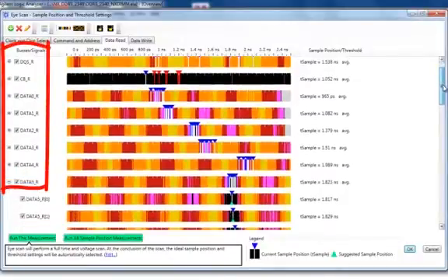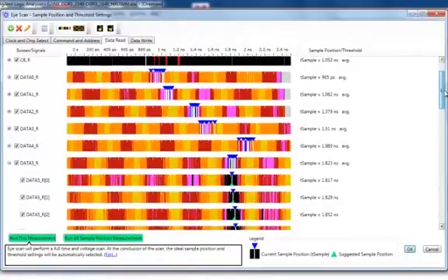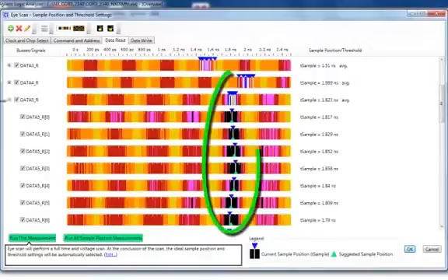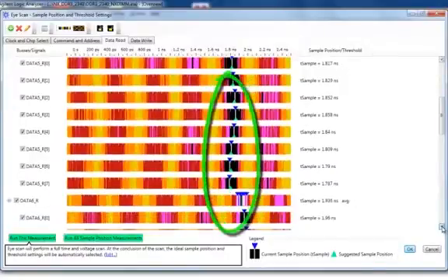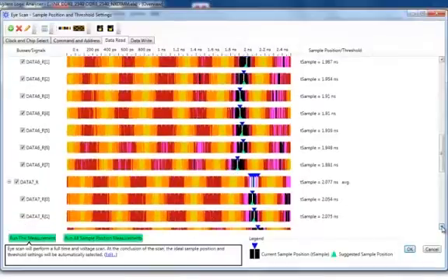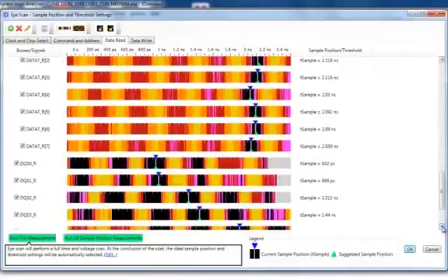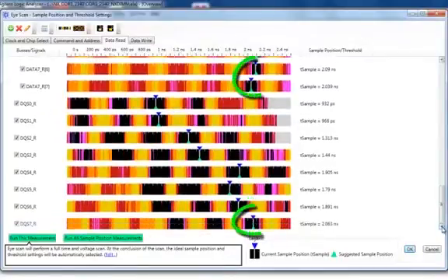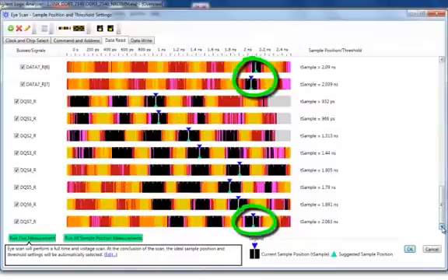The composite signals do not show an eye because the eyes are very small and overlap. There are no check bits in this system. But we can see the byte lane activity of the composites. And then when we open up an individual byte lane, for example here, byte lane 5, we see the individual eyes. And then the composite of byte lane 6 and its eyes, and the composite of byte lane 7 and the eyes for byte lane 7. Also notice that the strobe should be corresponding to the sample positions for their specific byte lane.